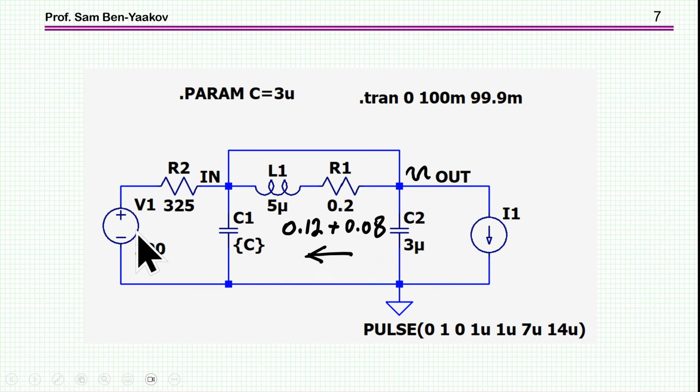And then this is a voltage source, and the resistor here is sort of decoupling this voltage source so it won't affect this capacitance. This is like, say, a power supply which is injecting a current into the unit. I put DC here just to make it more realistic that we have some DC, although it's not that important because we are dealing only with the ripple component here. And here I have a short because I'd like first of all to see what is happening without the ferrite, and then we'll see how the ferrite is helping or not in this case.